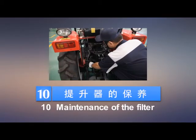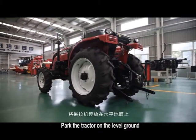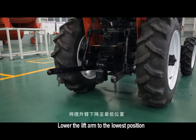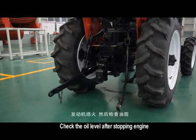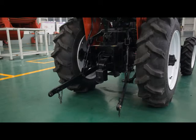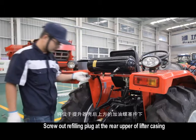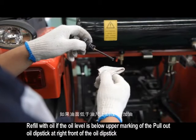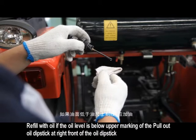10. Maintenance of the lifter. Attentions: park the tractor on the level ground. Lower the lift arm to the lowest position. Check the oil level after stopping engine. Screw out refilling plug at the rear upper of lifter casing. Refill with oil if the oil level is below upper marking of the pull-out oil dipstick at right front of the oil dipstick.